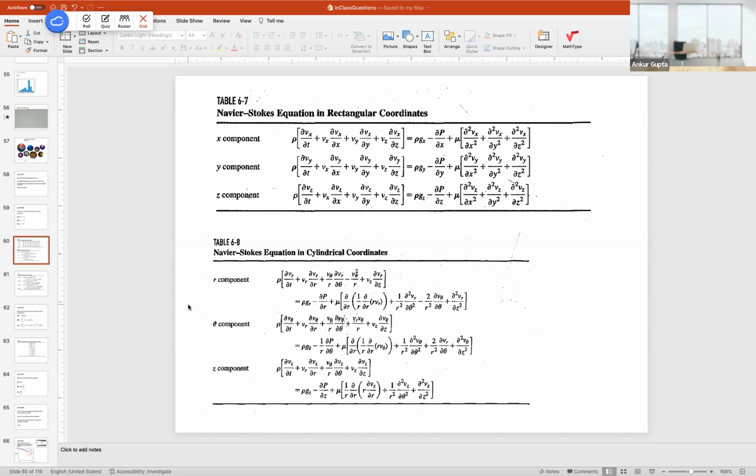Last class, when you were talking about the disk problem, I mean the air hockey problem, you wrote that because the r component of the velocity is dominant, the derivative is with z, normally del squared V_r by del z squared. So this still has to hold. Let me put the arrow here. This is the term that stays for the air hockey problem, because V_r is dominant with the derivative in z. But in the cylindrical problem, the first problem of your homework, where you have the sinusoidal variation, it's the z component of the velocity with the r derivatives.